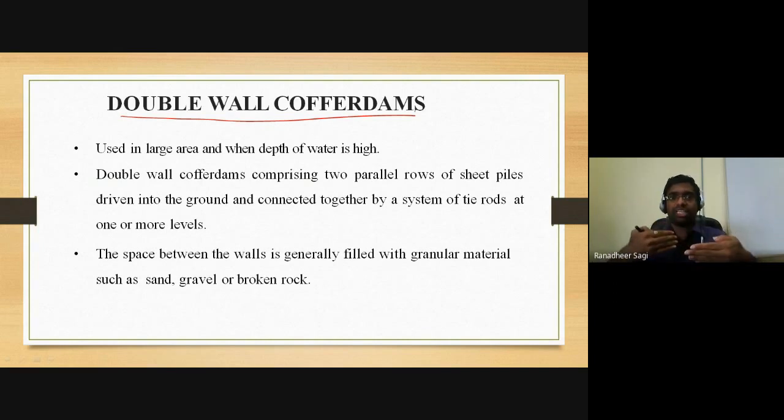So you are going to have, let's say, two sheet piles driven one adjacent to the other, where those two individual sheet piles are structurally connected by means of bracing once again, and those two sheet piles will certainly give you more resistance against the overturning effect because of tidal forces or any other external loads acting on the surface of your cofferdam structure.